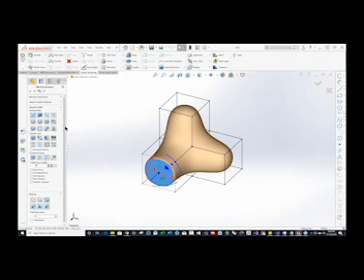And if I go to 100% of the weight, it produces a fully creased edge. So this edge is now a crease. So there will be a separate edge here. And in fact, when we get into SolidWorks, I'll show you that in a moment, you actually will be able to fillet that edge. So you can control the creasing along the edge. That's one way to attract the soap bubble.